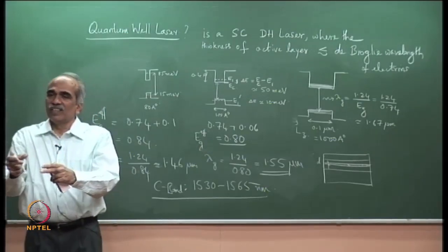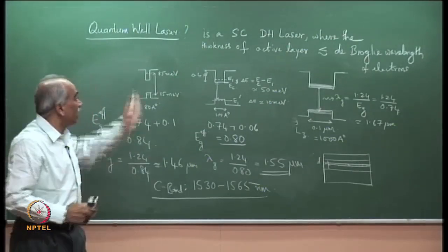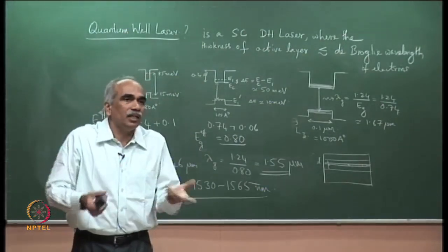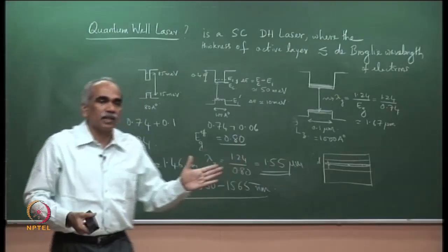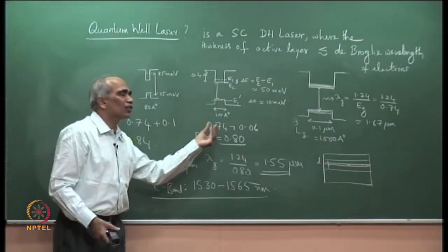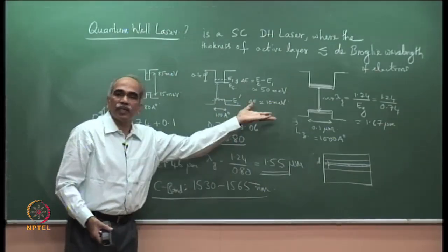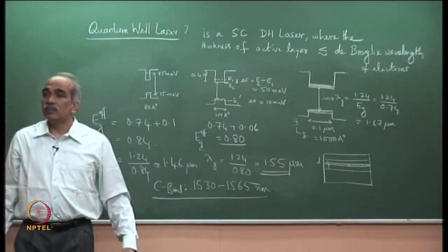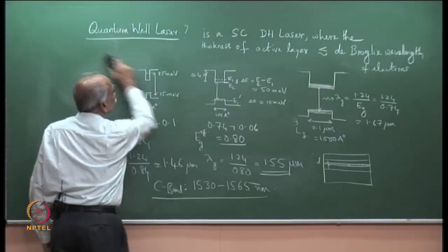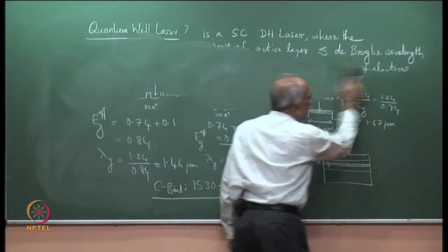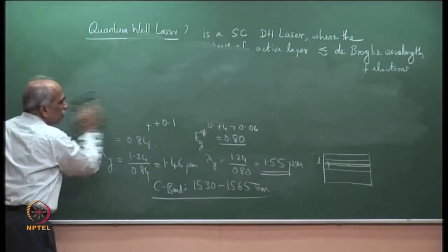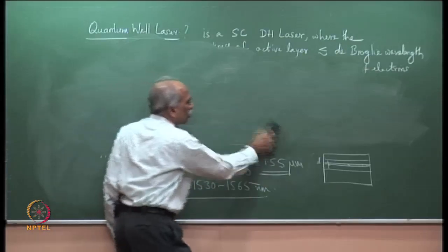Quantum well, each one of them is the same material. So, the material scientist has nothing to do, he does not have to change any process parameters. Everything is there, only deposition time is controlled from 80 angstroms to 85, 90, 95, and you can change the wavelength. This is a very important advantage in technology. So, this we have briefly discussed earlier, that modification of band gap by quantum well structures.